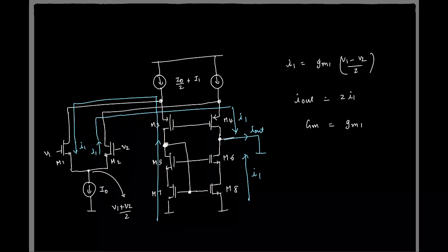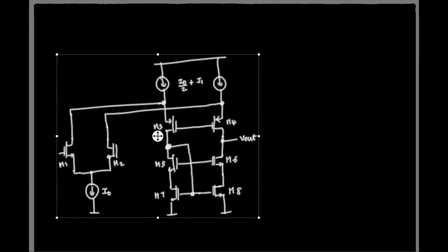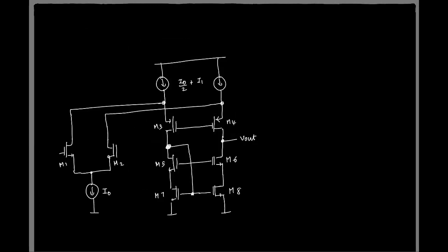Okay. Again, it shouldn't be surprising, right? The common source structure we have is still this guy. This is the differential pair that is sensing the differential voltage and generating the current. The only thing we have been changing all this time is the output impedance. Fine. So if this is clear, let's move on to the output impedance. Great. So again, for finding output impedance, you will find the looking down impedance, looking up impedance, and so on.